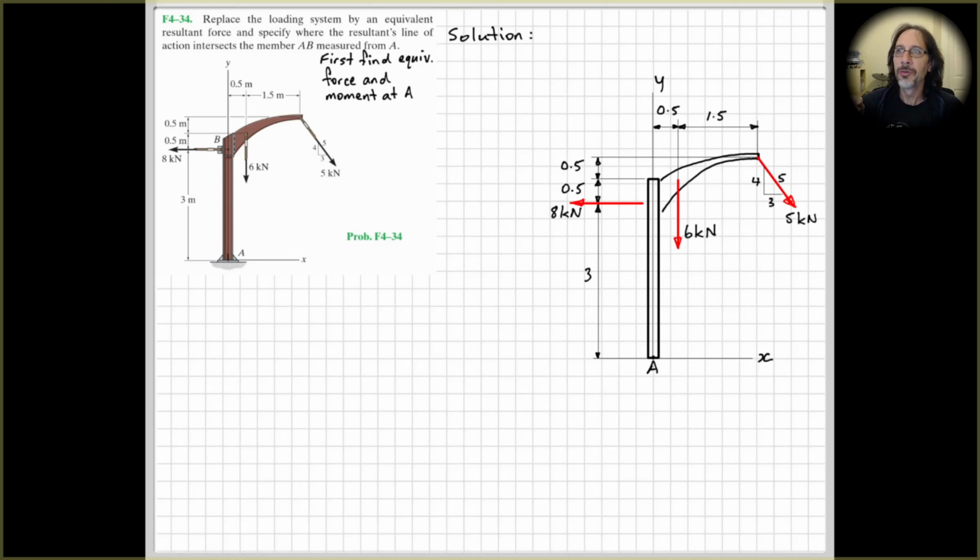Actually take the time and make sure that your witness lines go to where they're meant to go to. Right? So, putting dimension lines on, they're supposed to mean something. So make them mean what they're supposed to mean. All right, so we've got our problem redrawn here.